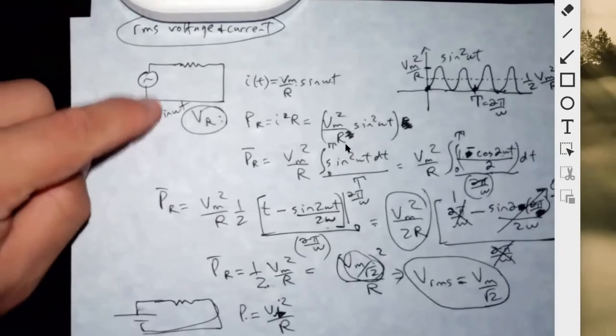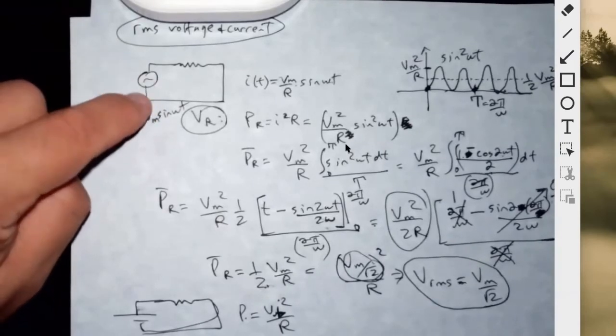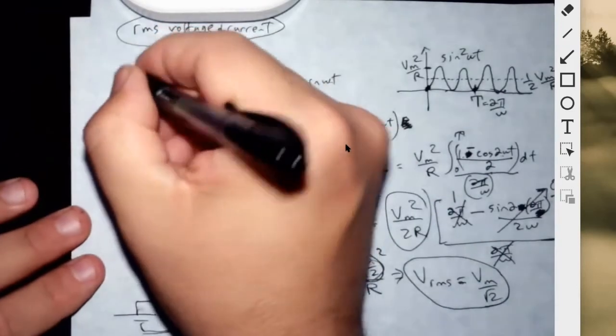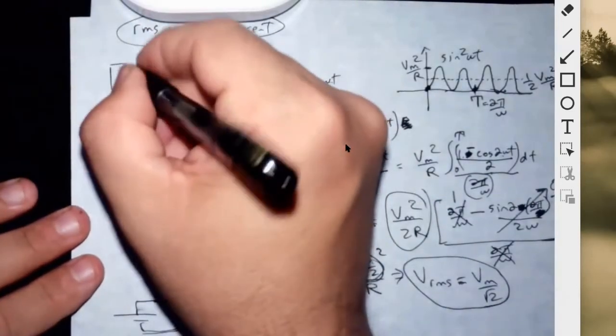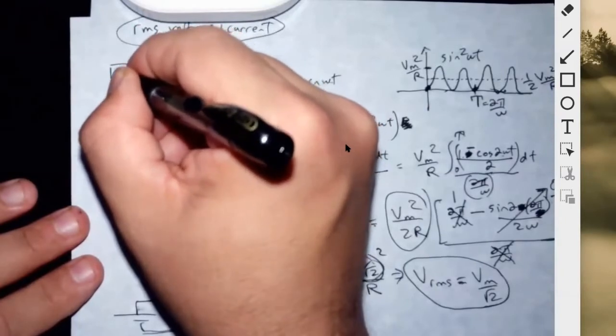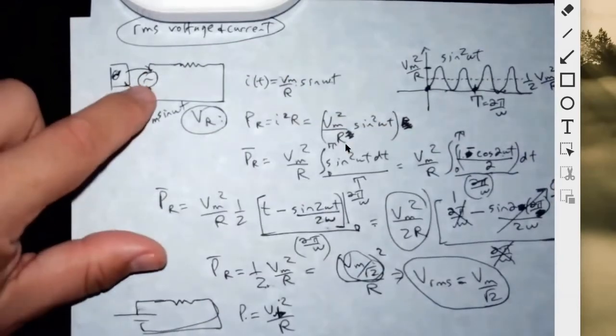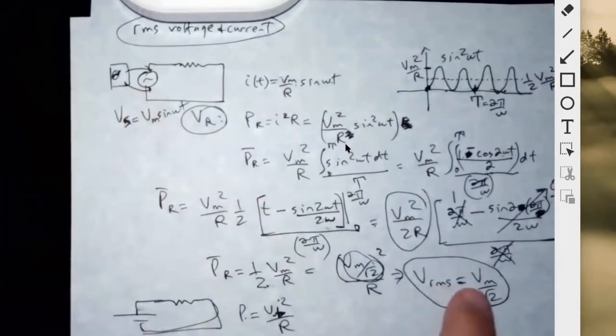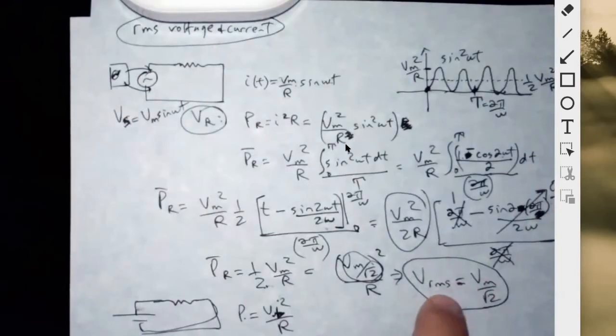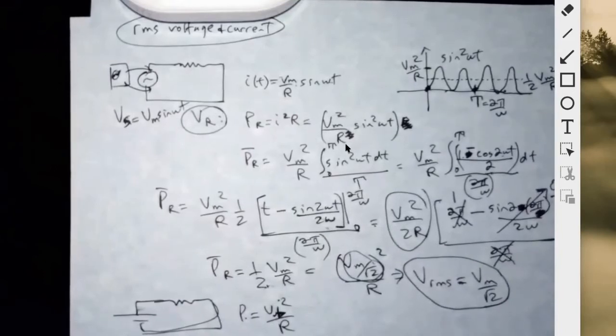So in order to measure the source's root mean square value, we usually take a multimeter and put it in AC mode. There's a little button that looks something like that, AC mode. Then we connect it across the source voltage, and that will give you the root mean square voltage. See, I even had a slip of the tongue, root mean square velocity from thermodynamics, but this is different. It's loosely related to that, but not really.